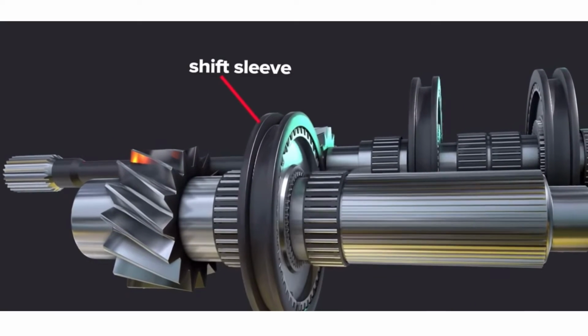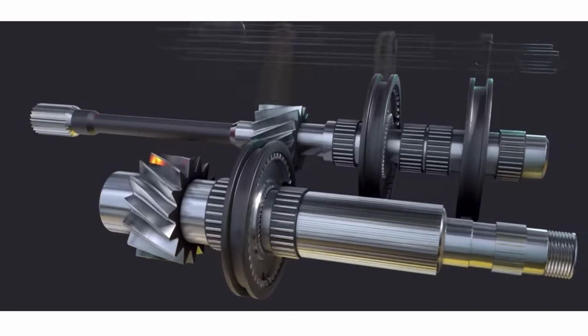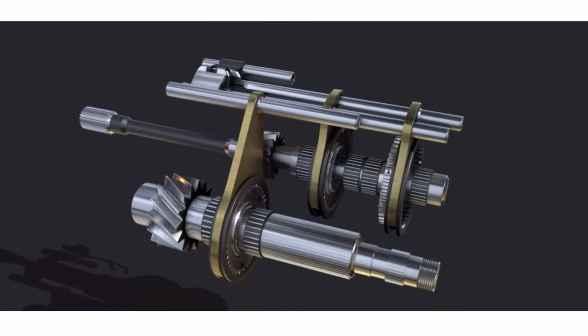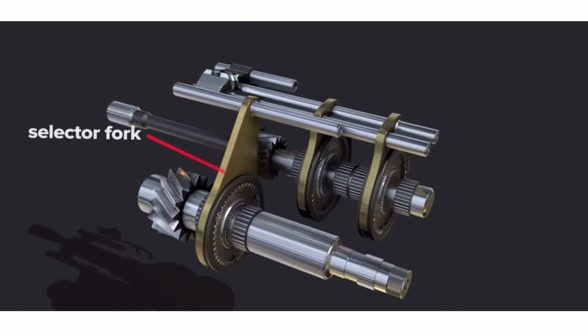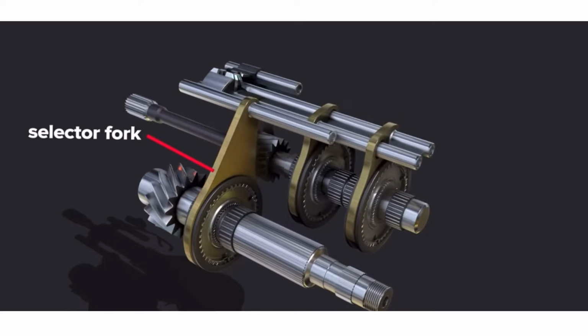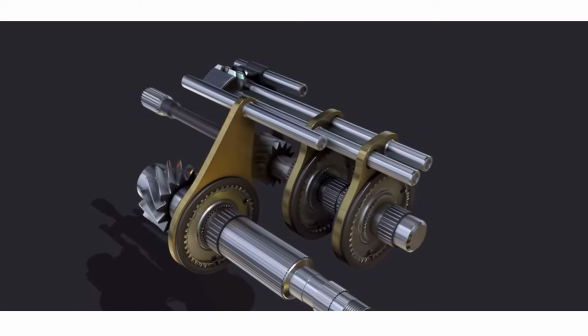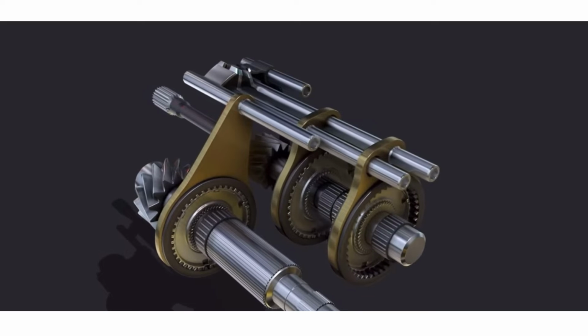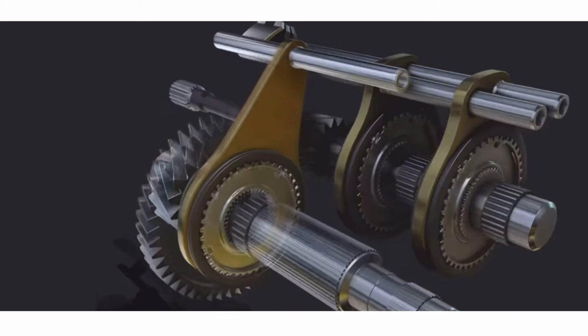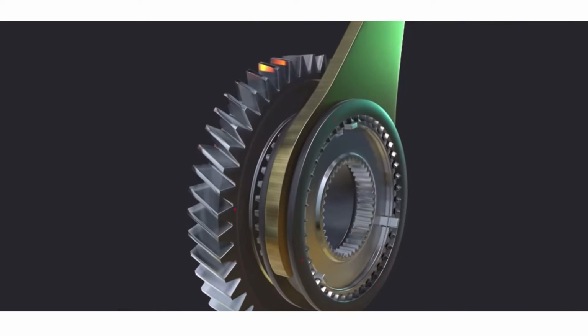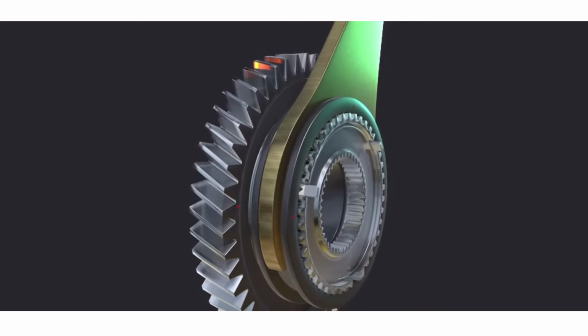In this type of gearbox, shifting occurs by the sliding of gears over the splined main shaft in order to mesh with the appropriate gear on the lay shaft, whose one gear is in constant mesh with the clutch shaft gear in order to carry rotational motion for the conversion, high torque or high speed, as required by the drive.